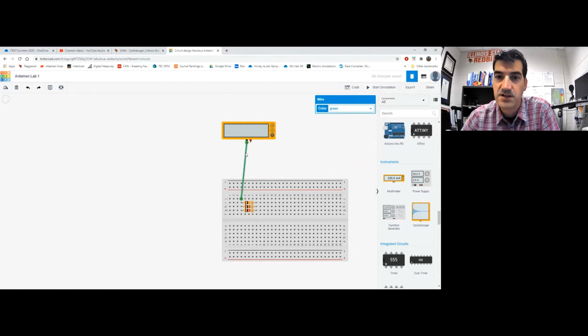So I'm going to click on the wire, and now I can move it anywhere around. I'm going to go vertically down like that, and then I'll double click here. And you can see it snaps to horizontal and vertical. So I want it to be like that. There, that looks pretty. And you can also change the color of the wire. I'll make this one black.